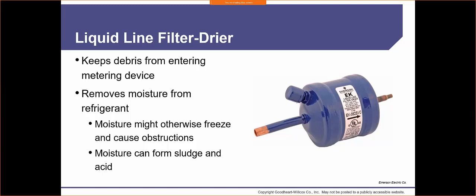Okay. Reason being, that filter dryer gets plugged up. We open the system up. Now it's exposed to atmospheric conditions again. It may plug it up some more, and so we don't know what happens. So we're just going to go ahead and put in a new unit. Okay.